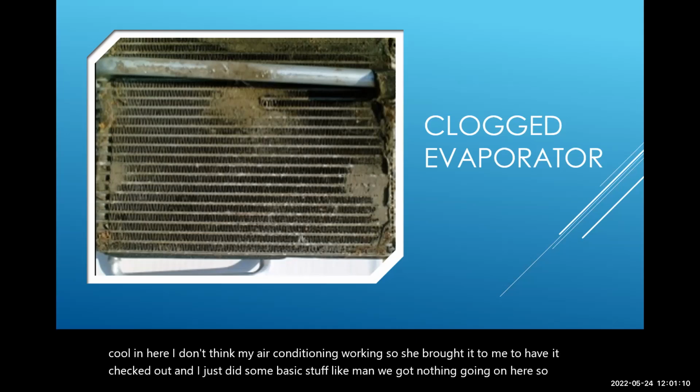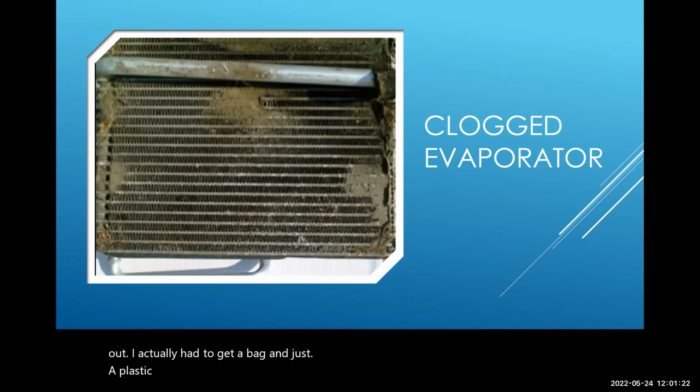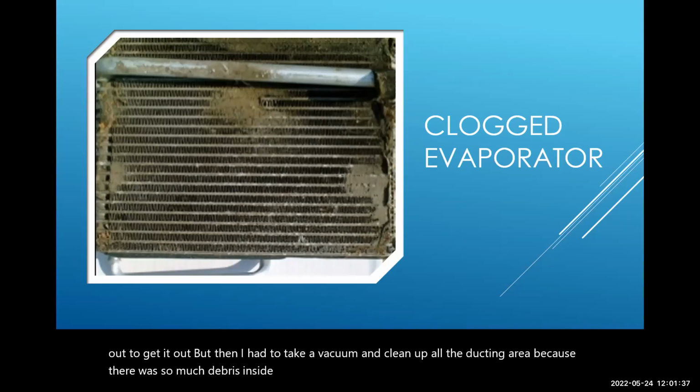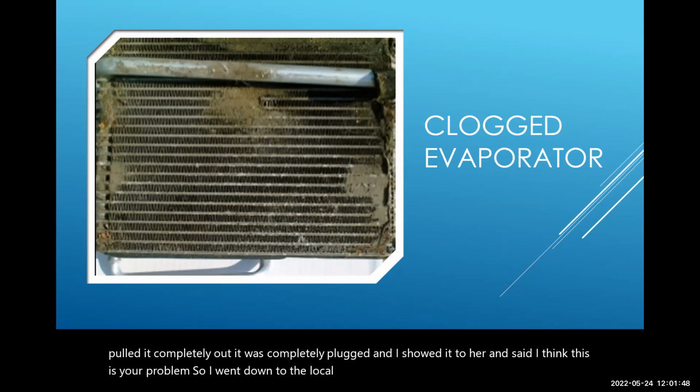So I went into the glove box, and that's where the filter was at. I pulled it out, and I could barely pull it out. I actually had to get a plastic bag and move it back and forth and almost force it out to get it out. Then I had to take a vacuum and clean up all the ducting area, because there was so much debris inside there that I couldn't get that filter out. And when I pulled it completely out, it was completely plugged. I showed it to her and said, I think this is your problem. So I went down to the local AutoZone and picked up one. They make them all kinds of different flavors, as I call it.